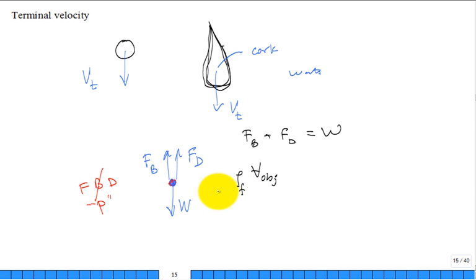That gives you the mass of the fluid that's displaced by the object, multiplied by g. Over here we'll put weight. What is the weight? It's the volume of the object, the density of the object, and g. The only difference between the buoyant force and the weight is whether you're going to use the density of the fluid, which seems abnormal, or the density of the object.